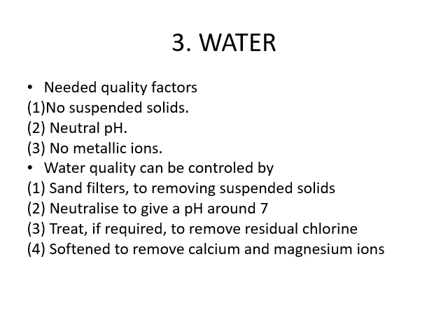Soften to remove calcium and magnesium ions, avoiding insoluble deposition of complexes on the fiber, due to which absorbency and feel of the fabric are affected. And the last one, treat to precipitate heavy metal ions to avoid degradation of fabric during chemical treatment, and also to control the final ash content of the fabric.